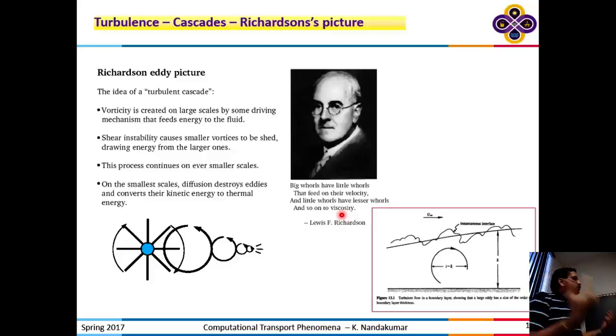So in all these fluid mechanical problems, we need to put energy to move the fluid from place A to place B. Whether it's a stir tank, or pumping the fluid from point A to point B, you are inputting energy. You are inputting energy typically on the large scale through rotating machinery, for example. And from that scale, the energy is transferred to smaller and smaller scales until it is dissipated into heat.